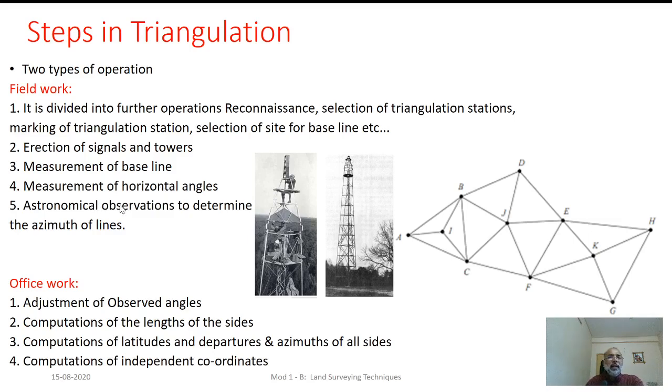In addition, there was a requirement for some typical stations termed Laplace stations, in order to make astronomical observations to determine the azimuth of a survey line. I hope you remember the bearing. We used to define the magnetic north direction, and for the initial survey line we were expected to measure the bearing by making use of a compass.